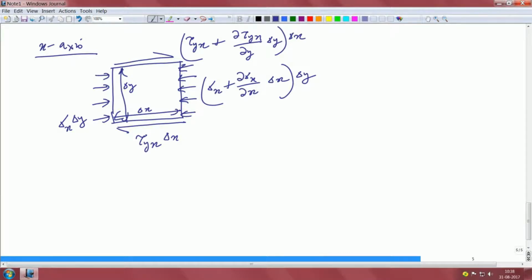So, forces can be of two types, one are surface forces and one are body forces. Similarly, you can have a body force which is represented by X, multiplied by delta x into delta y. So, that is a body force. Most of the useful examples of body force are gravity. Gravity is one example of a body force. We are not commenting on the nature of the body force, we are just putting it as X. So, these are basically the forces that are acting on the control volume, right. That takes care of the sigma Fn, these are the forces, right.